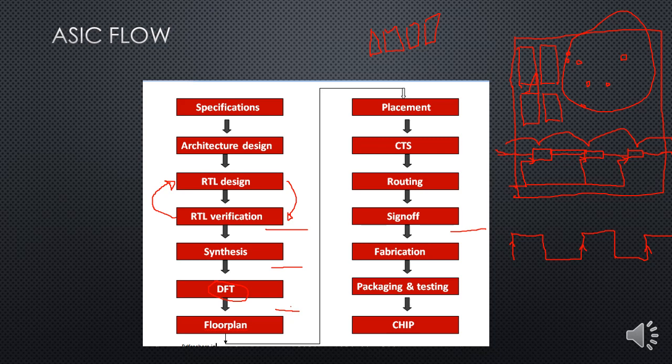But as I said, everything needs to be verified. So one of the important steps is sign off. In the sign off step, we test whatever we have achieved, whether we have converted the logical thing to physical format and realized that logic or not. We have multiple, various kinds of checks in order to scrutinize that and get that confirmation. We do that at this step, and then we can tape out the design. Tape out is the process of sending the data to the fabrication.